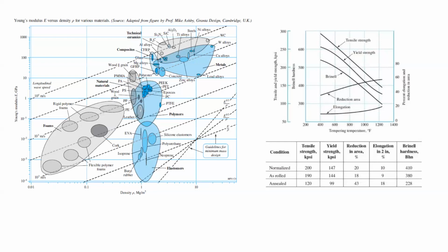So whenever you look up a material, not all materials will be made the same, even if you call it steel, right? You have the standard alloys or the chemical composition. So if you see something like 1020, that's referring to the percentage of carbon within the metal and the alloying metal that they use with it. All those codes are a little confusing at first, but all you should understand is there's certain alloys that you can put in metals to change their properties, but there are compromises, right? So 1020 has a relatively high carbon content, so it might be a little more brittle than one with less carbon content.